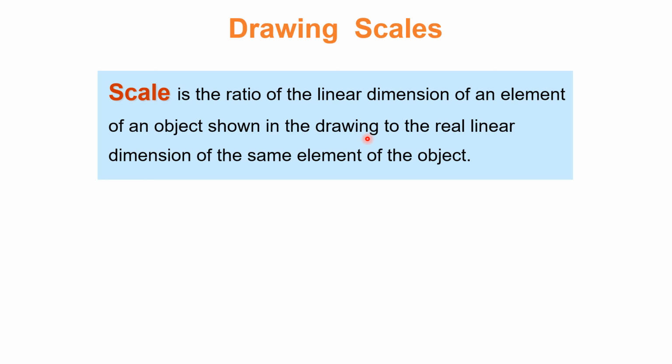are too big structures. If the length of a building is like 25 feet, we cannot draw this line at 25 feet on the drawing. Our drawing size is limited, so we will scale it, like 1 foot equal to 1 inch. So we only draw a 25-inch line, and that dimension can be drawn on the drawing. You can use any suitable scale, like 1 foot equal to 1 centimeter. That's how we scale the bigger structure onto the drawing paper.